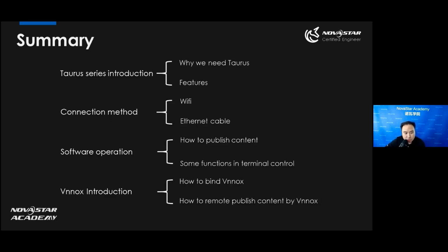The third part is the software operation, and we introduced how to publish content with the Vplex Express and some useful functions in the terminal control page, such as the playback management, the brightness adjustment, and the terminal upgrade. For the last part, it is the Vnox introduction. We introduced how to bind the Taurus series cards to our Vnox account, and how to do the remote publish control, how to do the remote publish content by the Vnox. And this is all about today's course.